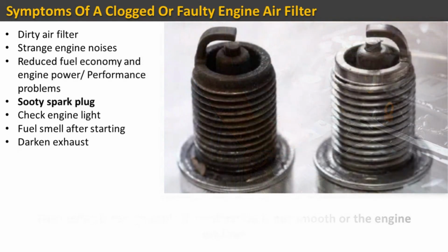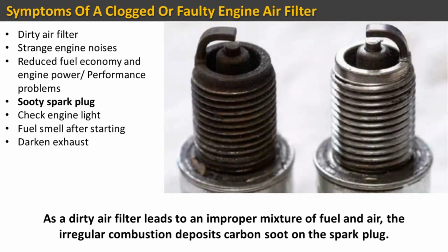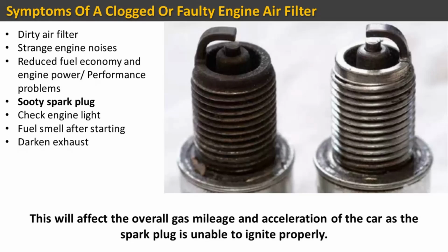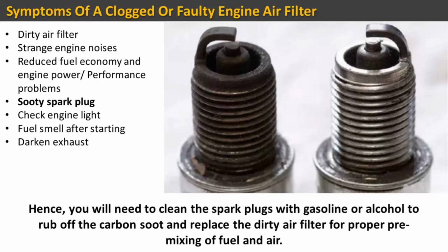Sooty spark plug. As a dirty air filter leads to an improper mixture of fuel and air, the irregular combustion deposits carbon soot on the spark plug. This will affect the overall gas mileage and acceleration of the car, as the spark plug is unable to ignite properly. Hence, you will need to clean the spark plugs with gasoline or alcohol to rub off the carbon soot and replace the dirty air filter for proper premixing of fuel and air.